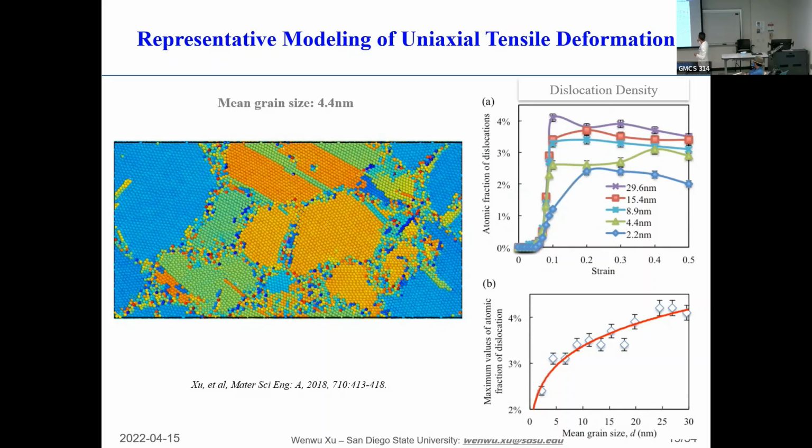And then we see there is a similar phenomenon like what we just talked about in the magnesium, that is with increasing grain size, the dislocation density is increasing relatively. And then this can be nicely described by this analytical curve. That is indeed, with increasing grain size, the dislocation density in a plastic range, flow stress range, is also increasing, not linearly, kind of non-linearly, right? And then, so this is just an overview.